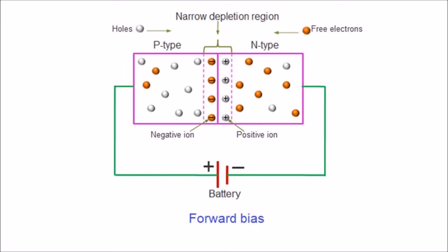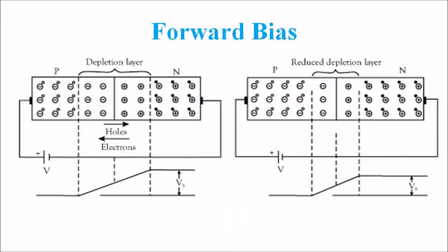With the forward bias, the depletion layer is narrow enough that the electrons can cross the junction and are injected into the p-type material. However, they do not continue to flow through the p-type material indefinitely because it is energetically favorable for them to recombine with the holes. The average length an electron travels through the p-type material before recombining is called the diffusion length, and it is typically on the order of microns.